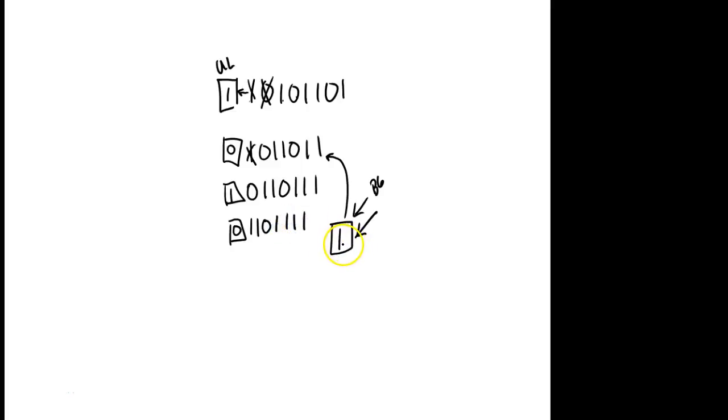So we specify the bit that's going to come in on this side over here. That's not going to change unless you change it. So eventually you're going to end up with all 1s. After 7 shifts, we would end up with all 1s. Now you have to understand, this guy right here is still going to shift. You're shifting the entire 16-bit word. So if this is bit 0, 1, 2, 3, 4, 5, 6, 7, then bit 8 here would have gone to a 1, because it's going to shift the entire 16-bit word. And if I shift 16 times, I would end up with all 1s.